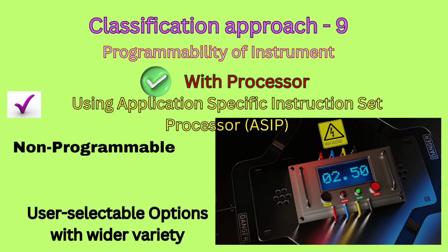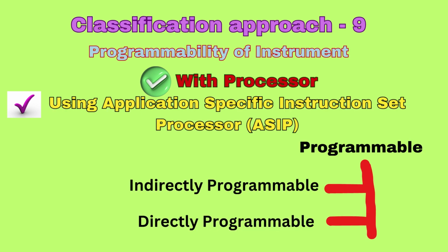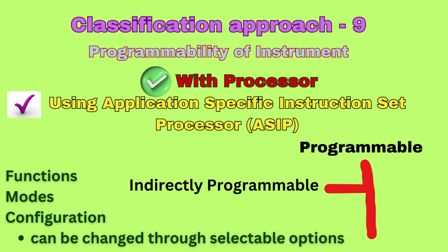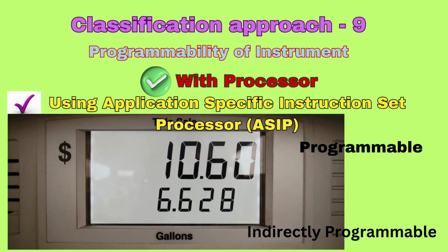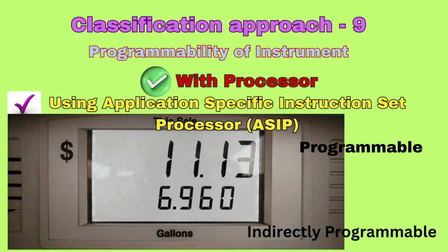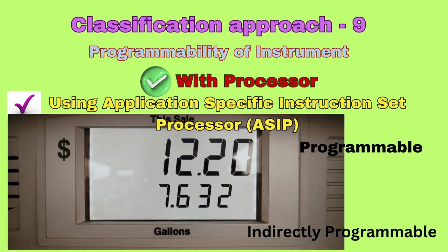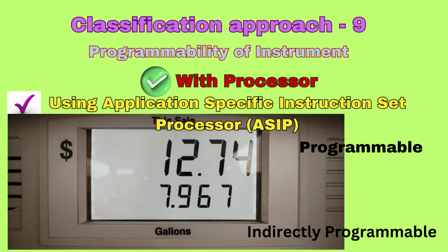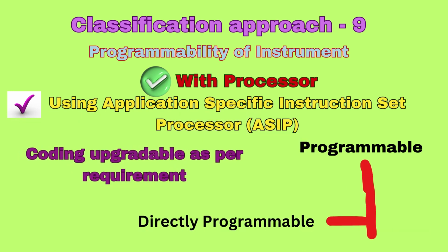Microcontrollers are application-specific processors that can be programmed and sometimes reprogrammed. When reprogramming is open, it is performed by the designer of the instrument by changing source code. The user can enjoy the final product only, but with some liberty of altering the available options. Thus, the instruments can be either indirectly programmable with the ability of altering options or directly programmable by altering the source code.